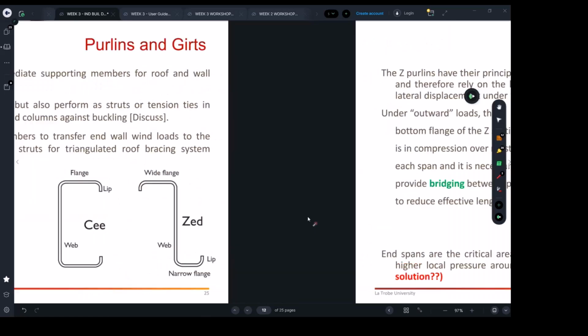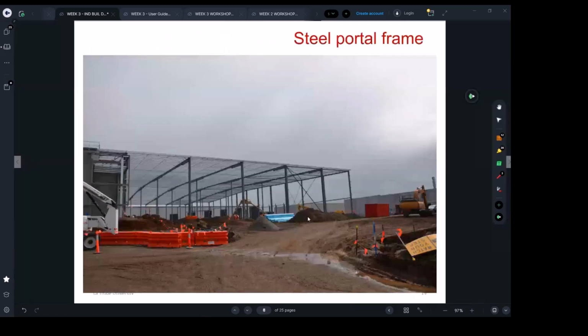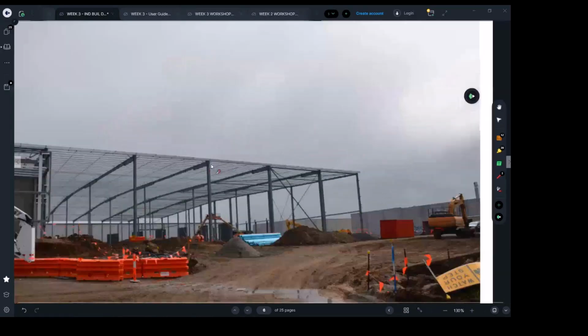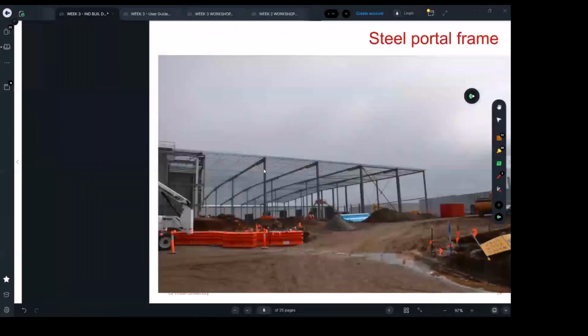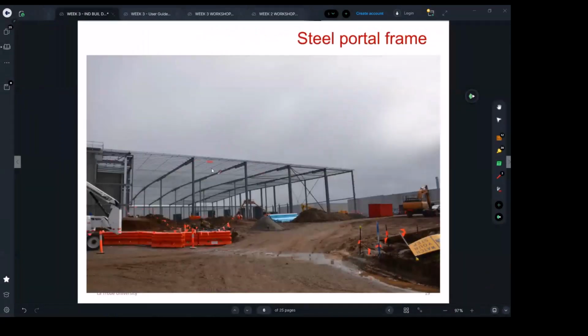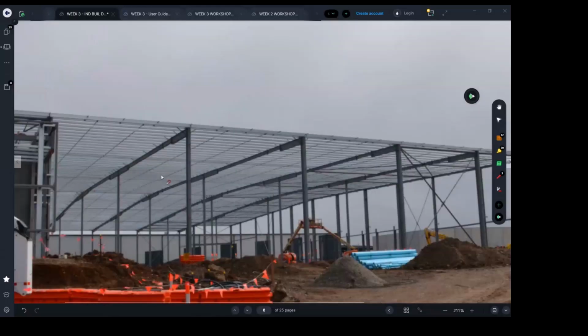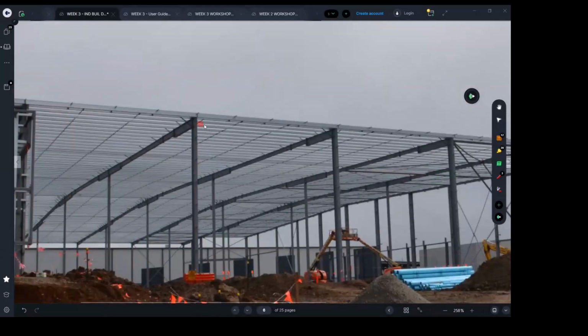Or I give you an image like this, zoomed, a clearer, closer picture, as we're going to see later, and I tell you, clarify what is the function of this purlin. One of them, I'm telling you now, is to support the sheeting material. Number two, tell me, what's the second one? That's a question for maybe 3 marks.